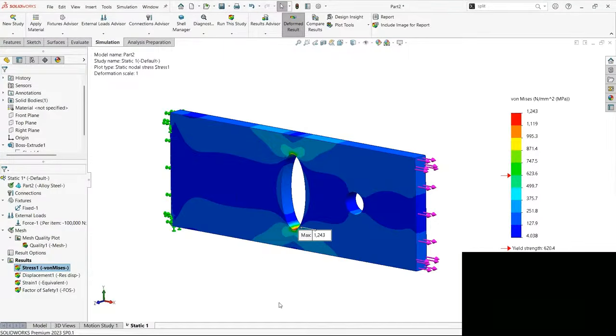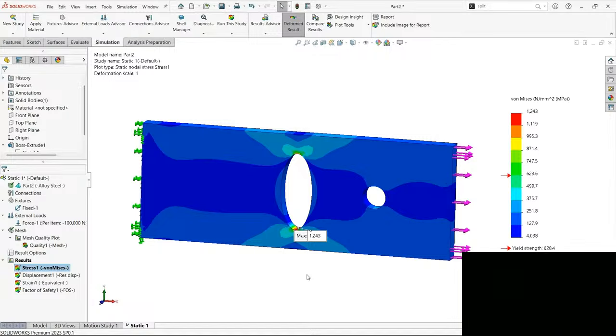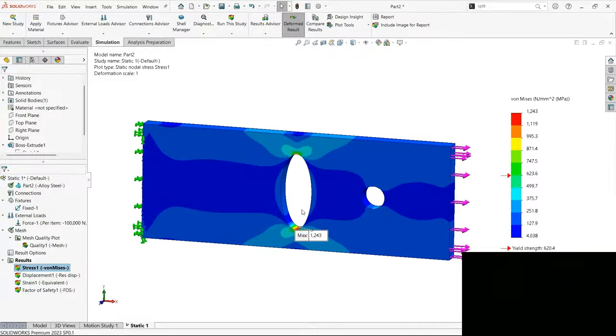Now, I hope you understood, right? So how you make your design, and all the things you need to consider in short to make the analysis better. See, by just changing the circular shape to an elliptical shape, the stress hotspots have drastically increased. The model was performing better, but just a simple design change made my design worse and it is completely failing. This kind of analysis is what you need to do, and you need to tell your counterparts or the vendors. You need to check everything, and then tell them this is what is happening.